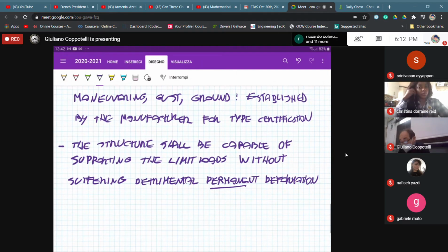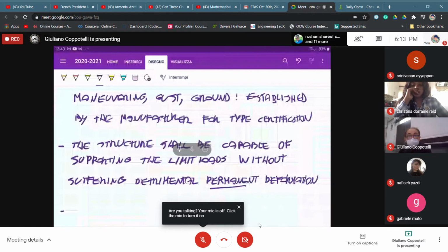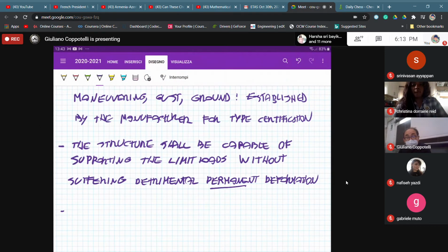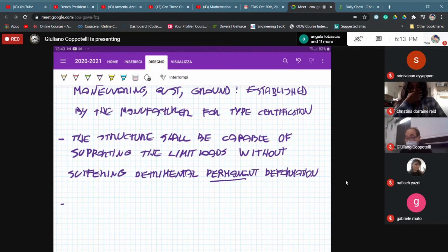Moreover, I would say that when we are considering all the loads that are characterizing whatever flight condition, and all these loads up to this limit, the deformation that your component, your aircraft is having as a reaction to that should not interfere with other components, with the normal flight operation. And that is the point of the safe operation that we have to check, okay? Just by checking that everything is happening without displacements that are unlimited. But they are limited, they are very nice, they are not interfering with each other. This structure is safely withstanding the external loading.